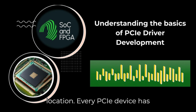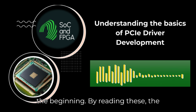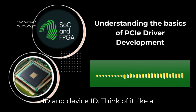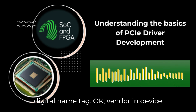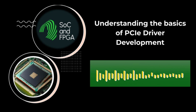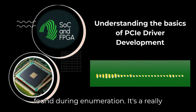Every PCIe device has standard configuration registers right at the beginning. By reading these, the system finds the device's unique vendor ID and device ID. Think of it like a digital name tag. Okay, vendor and device ID. Yeah. On Linux, you can use the lspci command to see all the devices the system found during enumeration. It's a really useful tool.